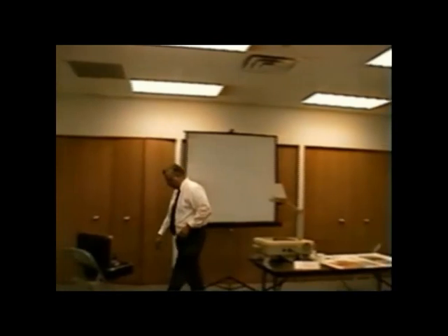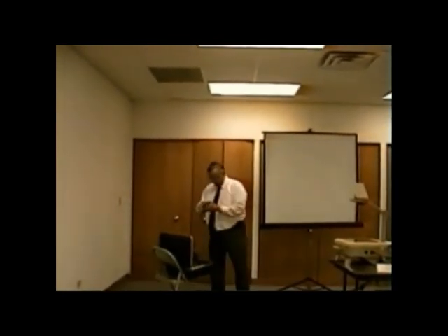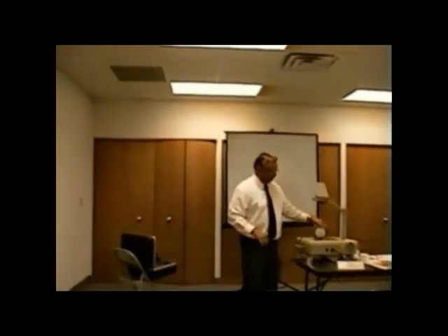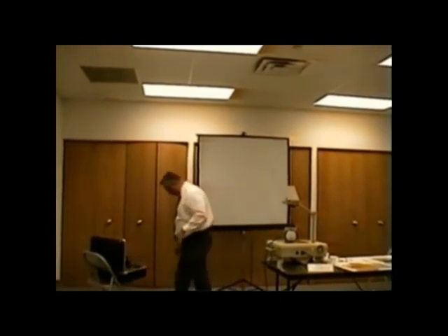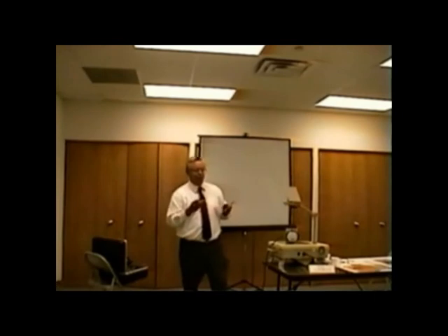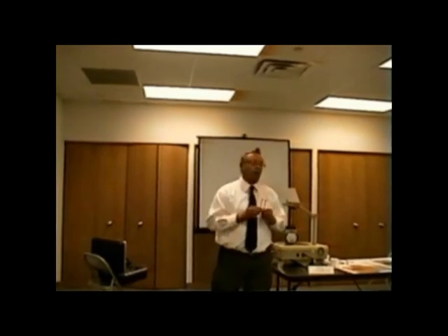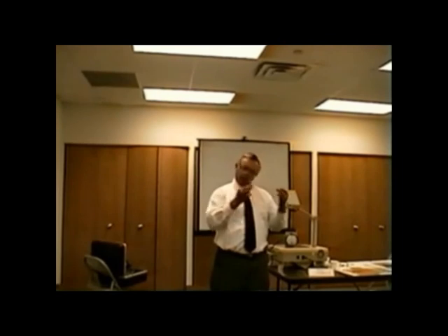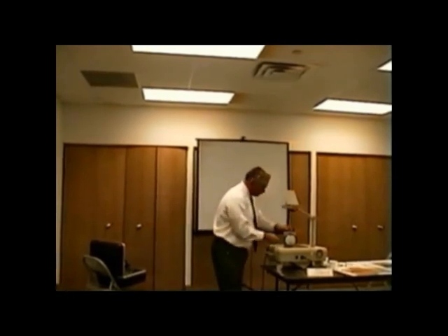Maximum external static pressure. You're going to use a couple of instruments. You're going to go back and use the magnehelic, and you're going to use a couple of Dwyer probes. And you're going to stick them in the ductwork. You're going to take one of these probes and stick it into supply, and another one you're going to stick into return. That's all. Let me explain a little more.